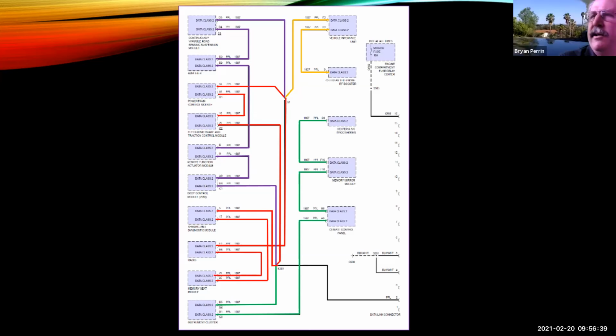You see kind of how I did that? So there's not one way. The idea is, how is information getting shared? How is it getting transmitted? And then how does this relate to either what codes I have or which modules I can't communicate with? And by doing this, now we can localize it down to where here's where my fault should be. Here's the wire that's probably bad.